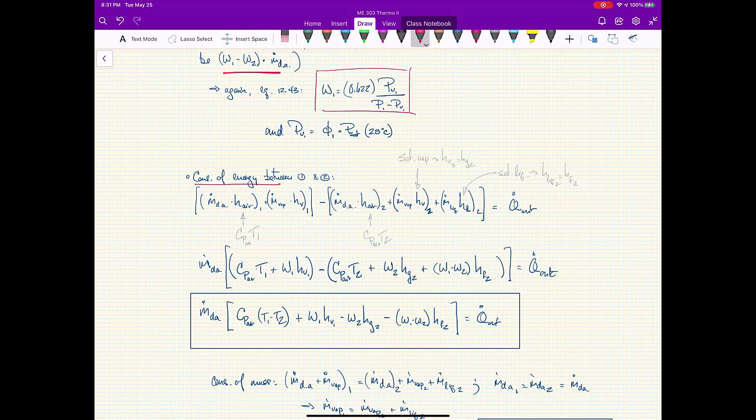Basically, what I've got is this cooling coil extracting stored energy from my flow between 1 and 2. So that means that the energy at 1 minus the energy at 2 is going to be equal to the amount of heat that's being taken out.